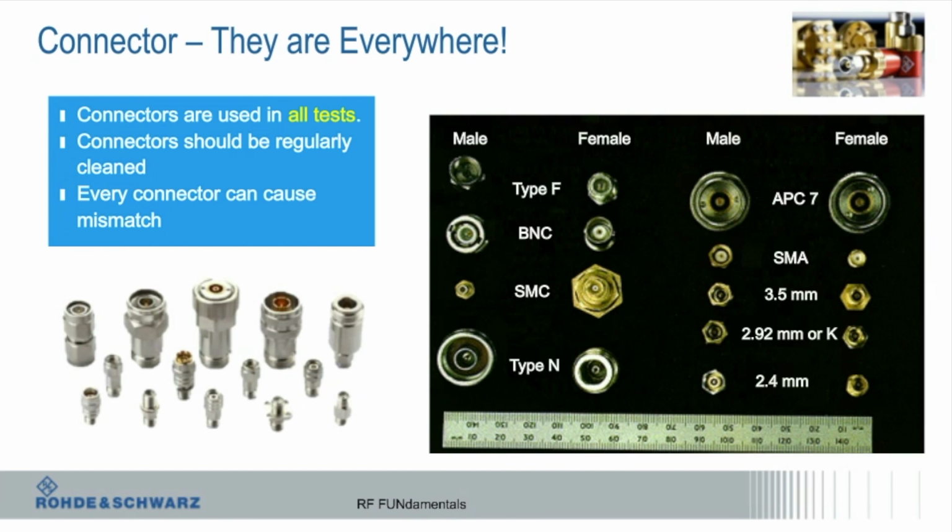You get lint in there. They get bent, and it will degrade your signal dramatically if it's damaged or dirty. So always look at them. Ideally, you'd look under a microscope. Not that I do that, but in principle. It should be regularly cleaned.